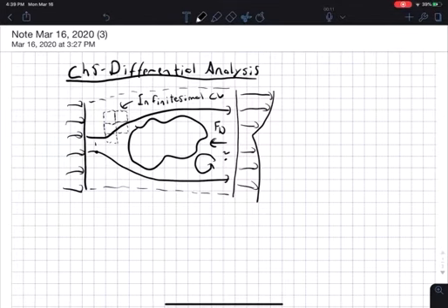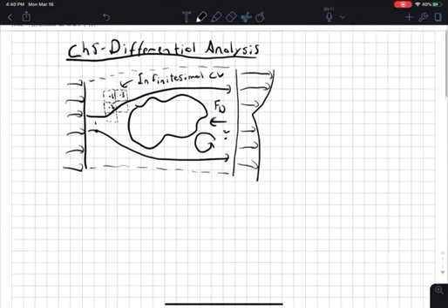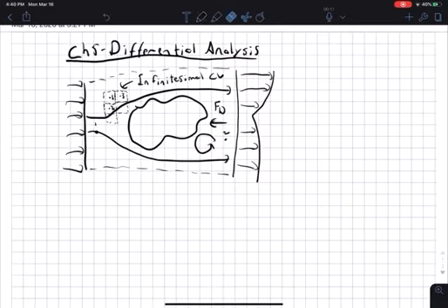And so here we can find the density at the center of this control volume, call that 1. We can find another density at the center of that control volume, say 2, and the density at the center of control volume 3, and so forth. In each of these control volumes we're finding an average density, but if we shrink these control volumes, of size delta x, or delta y I should say, to where each is essentially the size of a single point, and we have an infinite number of these infinitely small control volumes, we can find the details of the velocity vector and the density and everything else as a function of position, and you can find all the little details of the fluid flow.